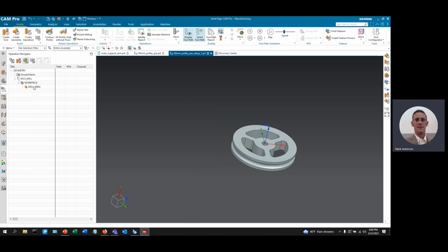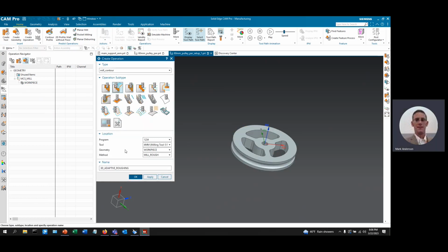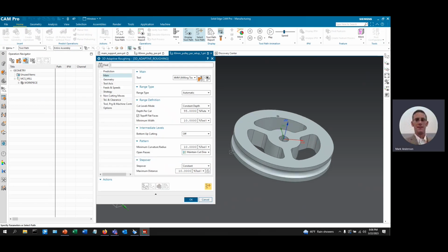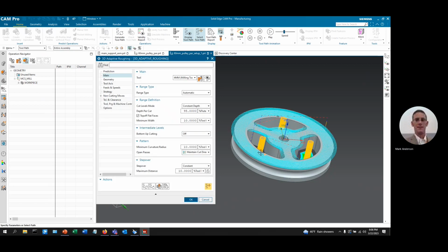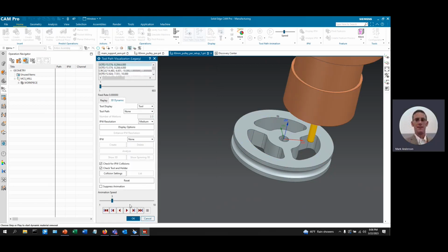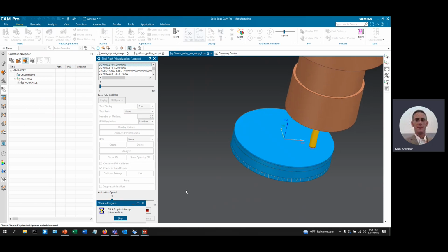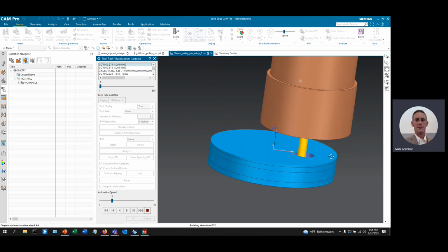And I'm going to show you another toolpath that is our high-speed machining strategy. This also looks volumetrically. So if I choose not to put any cut definitions in, it's going to do the entire part. Let me show you that. If I do go in there, let me go ahead and show you what this is. This is meant for long axial, very shallow radial cutting strategies. Very light machining, but very fast volume material removal.